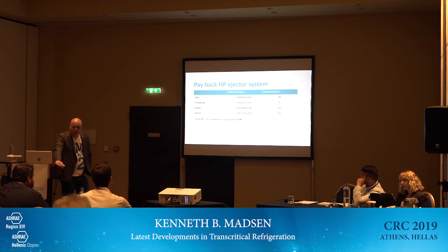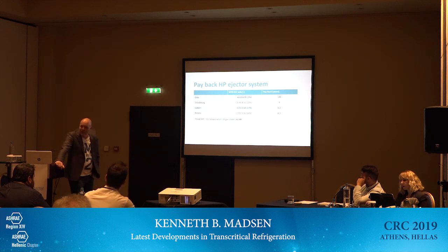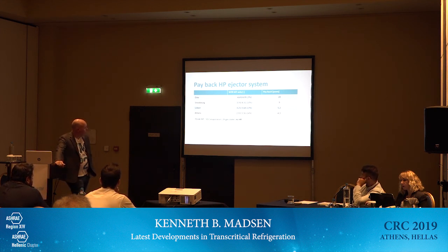So again, it of course all ends up with savings and payback time and stuff like that. So the two numbers you can see in the seasonal energy performance, the first one is the COP of a traditional booster, and the second one is the seasonal energy performance for a system with ejector. And you can see Norway is a cold country. The savings are very small because there's not a lot of fuel for the ejector. So 5% saving here, and the payback time here is around 20 years. And that is if we do a 70 kilowatt system.